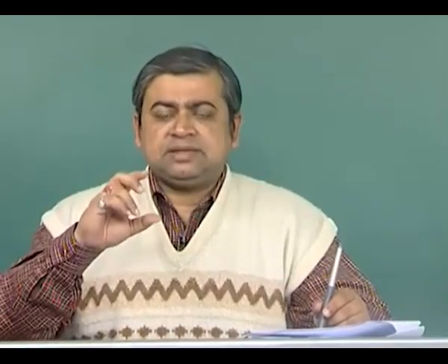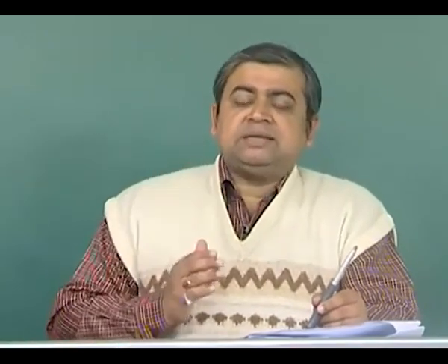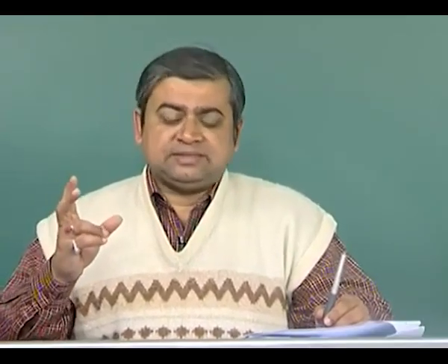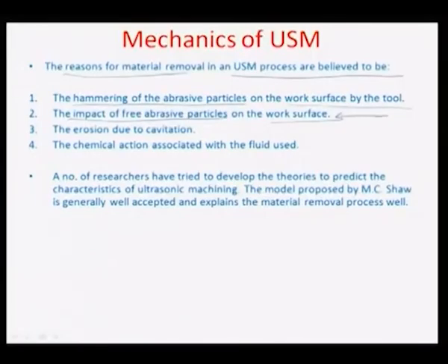When the tool is at its farthest position from the workpiece, there is a lot of gap where more than one abrasive particle can come. It can strike the tool surface, then come back and impinge on the workpiece surface. That aspect also needs to be considered in the material removal rate estimation. That is the impact of free abrasive particles on the work surface, as illustrated here.